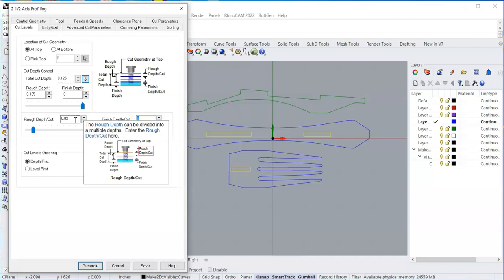So I know with a 1/4 inch end mill, 2 flute end mill in aluminum, I can take off anywhere between 0.04 and 0.08 depth of cut, okay? 0.08 if I'm being aggressive, 0.04 if I want to be able to run my machine a little faster in terms of how fast it's going around the material. I don't have to baby it. With a 1/8 inch end mill, I just know that 0.02, I could probably go 0.04 and push it a little bit, but I'm like, why do it?